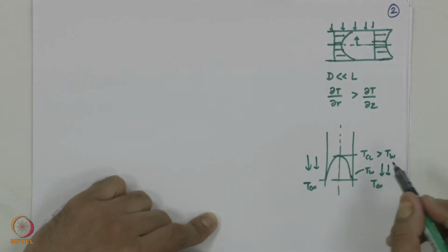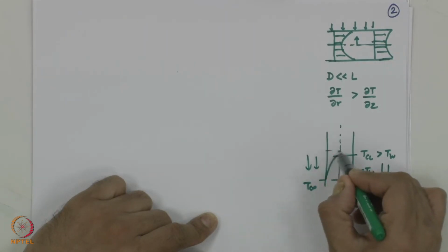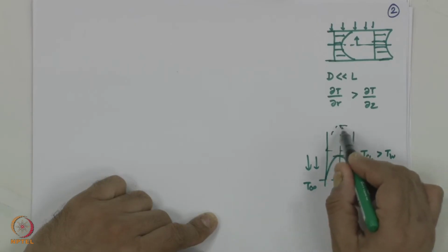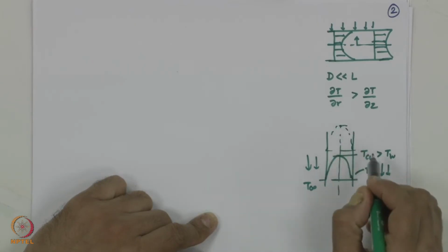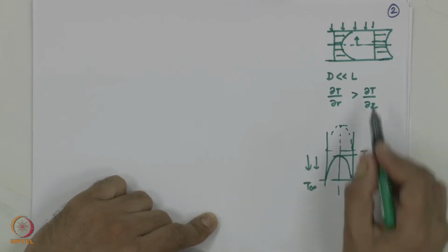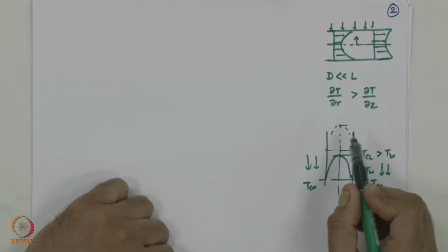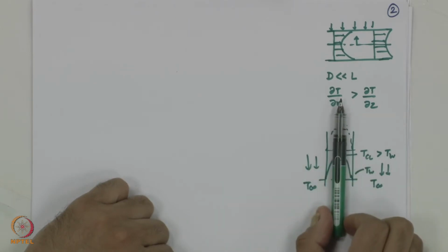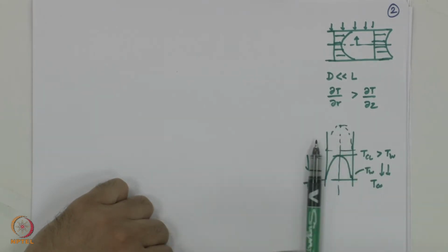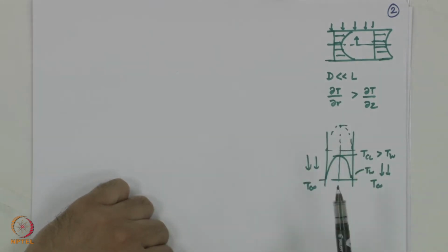So, you would say that the profile would kind of repeat itself with a small change in the magnitude, okay, if you are having heat transfer from the outside, or if you do not have any heat transfer from the outside, if there is a constant volumetric heat generation, every axial location is going to have the same kind of temperature profile.